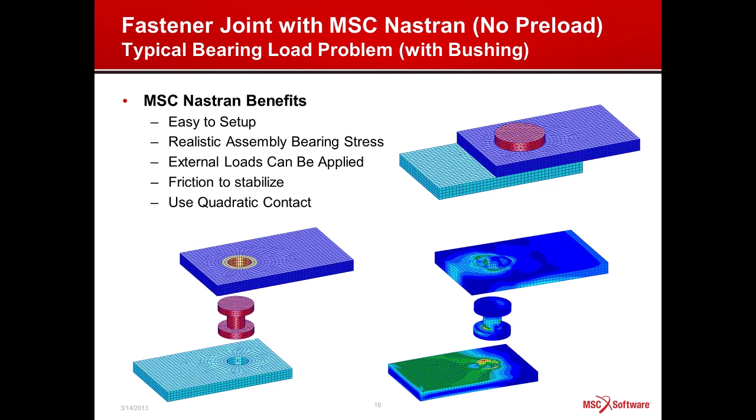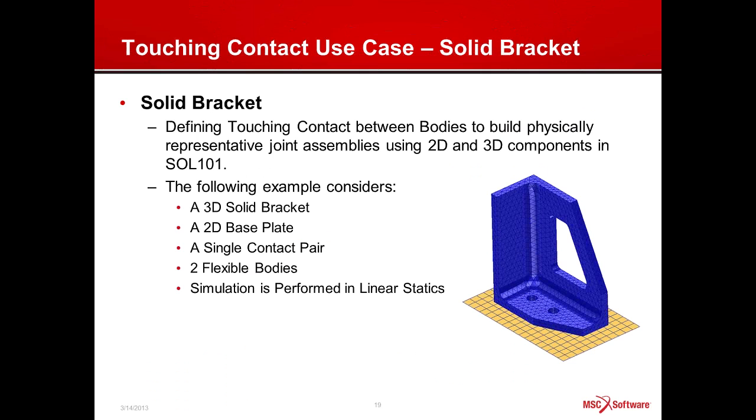Another example is a lap shear joint with a pin. There's a steel sleeve inside an aluminum beam, the blue and orange or gold shape colors, so you can actually have the benefit of integrating this all together by meshing the components as is, using 3D mesh very easily. And you notice here that for bearing stress in cylindrical holes, it's also good to have at least one of the sides meshed with hex brick elements. That's usually very good practice to get very good bearing stresses as well.